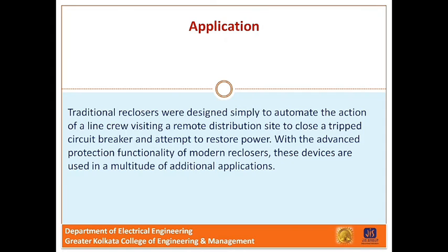Application. Traditional reclosers were designed simply to automate the action of a line crew visiting a remote distribution site to close a tripped circuit breaker and attempt to restore power. With the advanced protection functionality of modern reclosers, these devices are used in a multitude of additional applications.